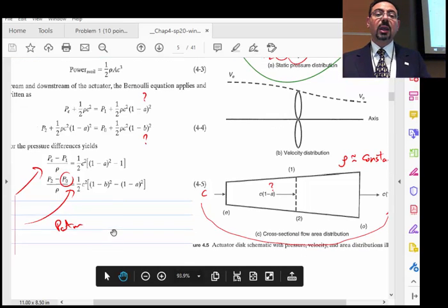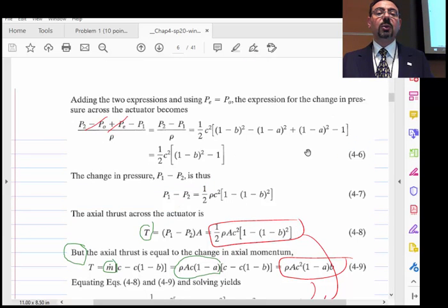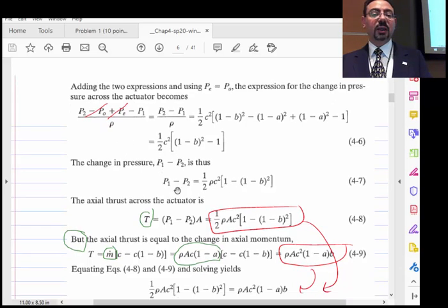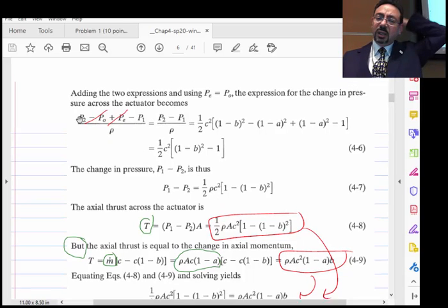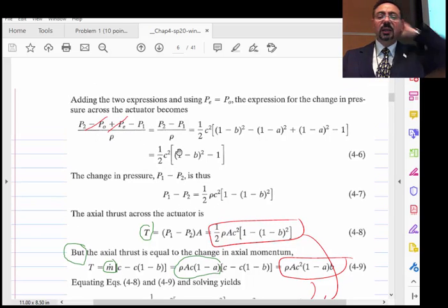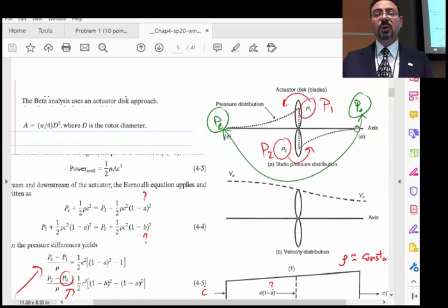Okay, so just having the continuity, momentum, and energy equations in those two places, you end up saying that P2 minus P1, that's the pressure before and after the turbine, equals this. Right? Simplifying, why were PO and PE cancelled with each other? Because they're atmospheric.